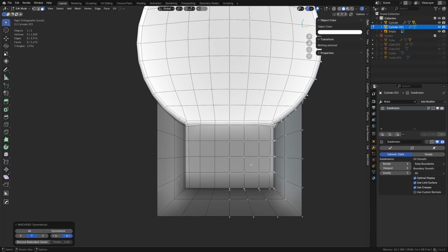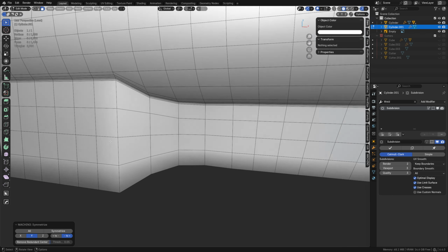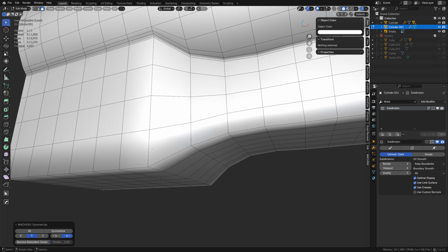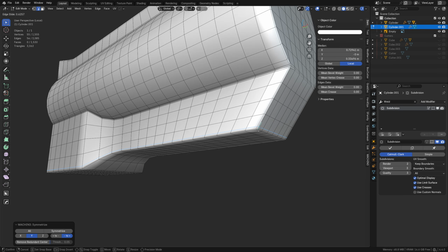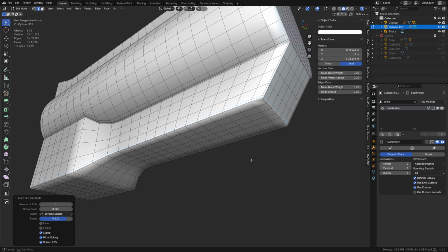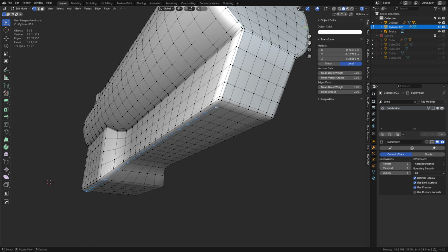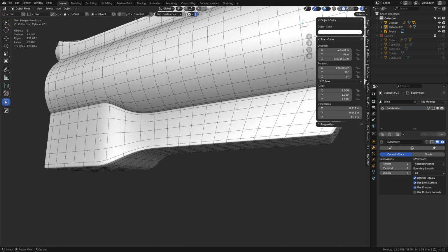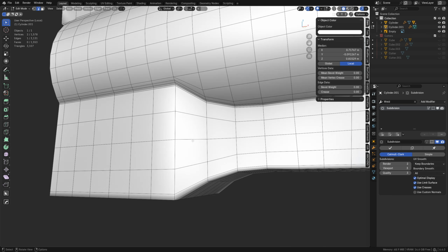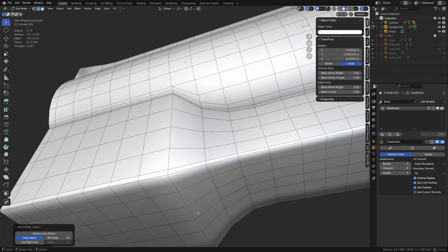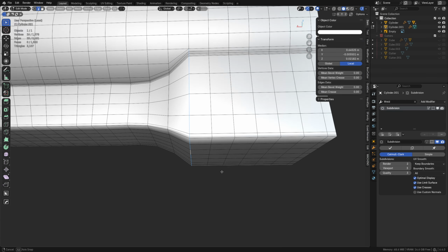And yeah, so we would have to go through at this point and just continue adding holding edges if we need them. A lot of times you can do them with loop cuts. You can use existing topo and redirect or shift it around. You don't always have to do a new loop cut. In our case, we already had a cut going there, so we're good. In this case here, I think I'm just going to try beveling it first and see what happens.